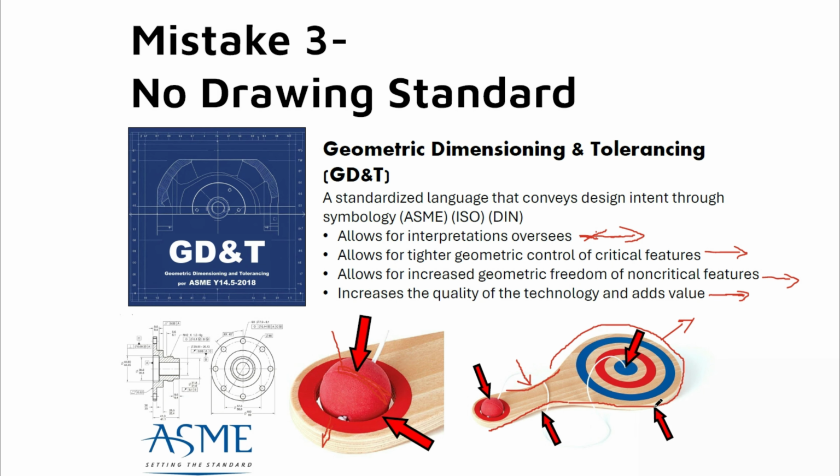And then we talked about the profile on the outside, keeping that maybe more loose, unless there is a specific paddleboard standard that we need to meet. And then we can obviously, through GD&T, make sure that our paddleboard outside profile matches that standard. And then also the position and orientation of this hole. So those are some of the GD&T controls I would put on this simple toy right here.